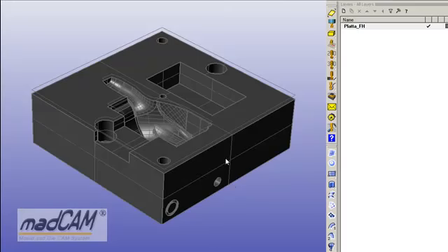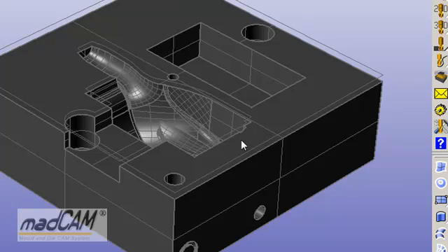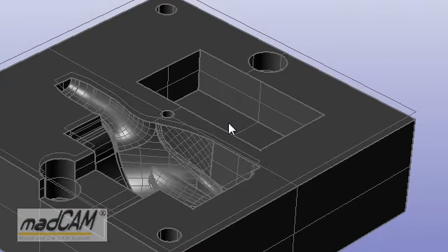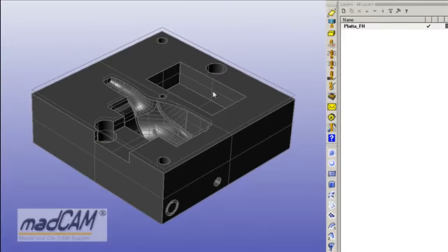This tutorial will show you how to use cap surfaces. It is possible to create cap surfaces from planar curves or from just closed curves in Rhino. You can then select them together with the model to prevent the cutter from machining some areas.